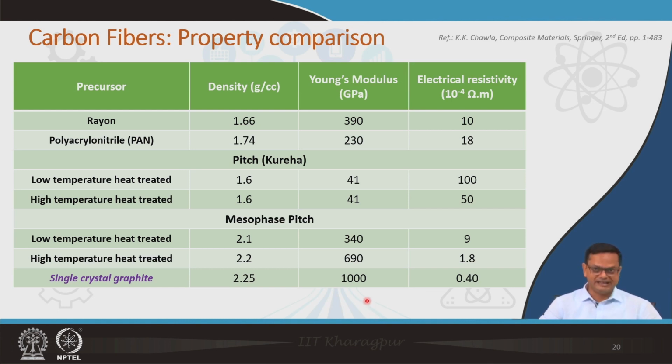these are perfectly hexagonal structures. So, the strength is basically theoretical strength, like 1 TPa. So, it is quite high. Ideally, these are ideal values, but in reality you do not reach that high a value. Still, you can see here the modulus can easily reach in the range of 600 to 700 GPa.